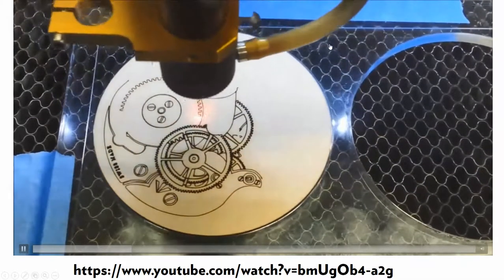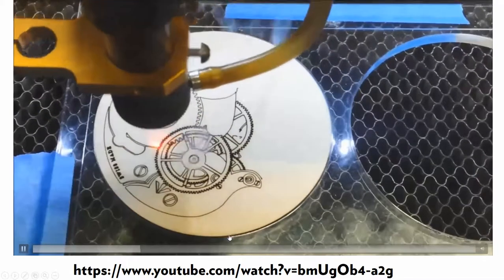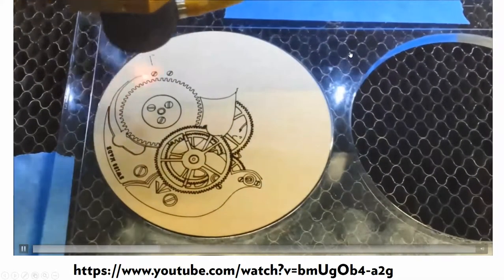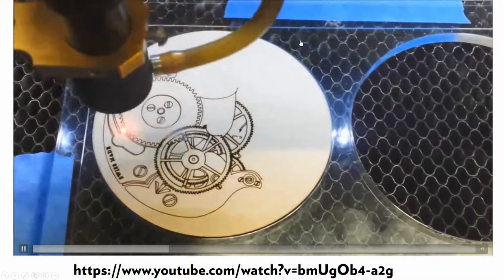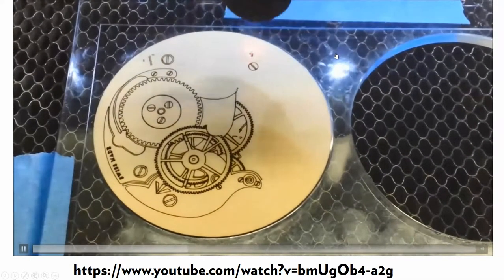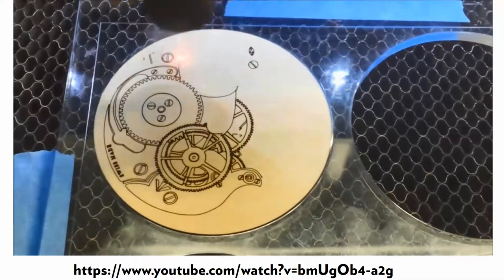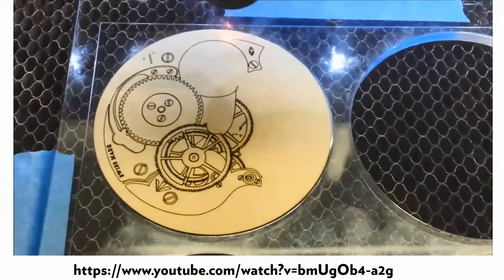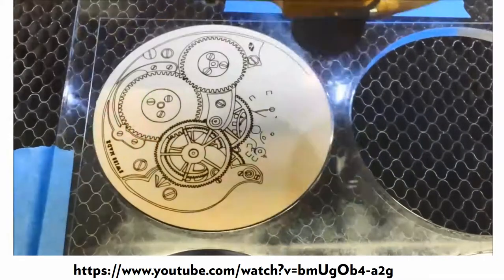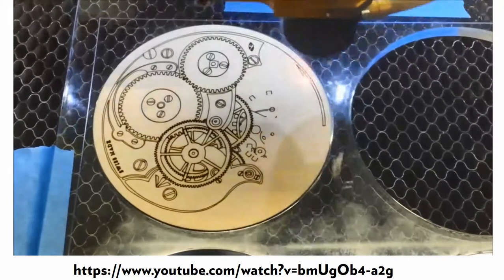Also notice that these people have cut in advance a clear plastic jig. So this is a little device. Looks like they cut it out of clear acrylic so that they can put these pieces of plywood in here, and that way it probably lines up with the pattern they've already created on their software program, so they don't have to align the image to the piece that they're cutting on every time. So often making jigs like this is a great time saver.